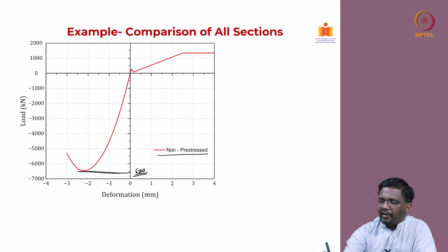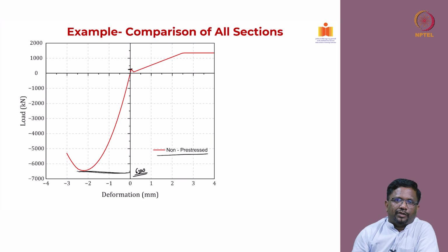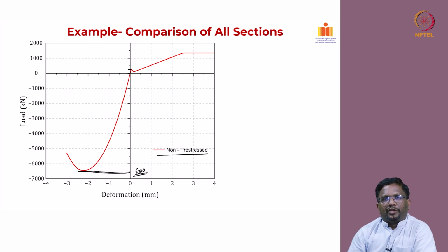And cracking is a very small value, right. We know how to calculate the cracking strength once you give your epsilon CR or epsilon prime T, right. This is a very low cracking load in tension, very high compression load, which is 6500. Cracking load you see roughly, if this is 500, is roughly about 250 or so, right.